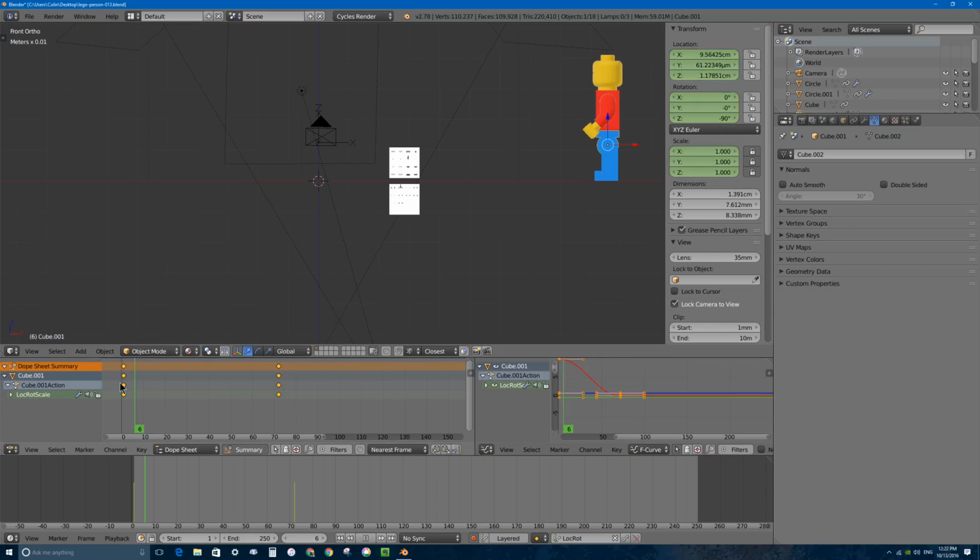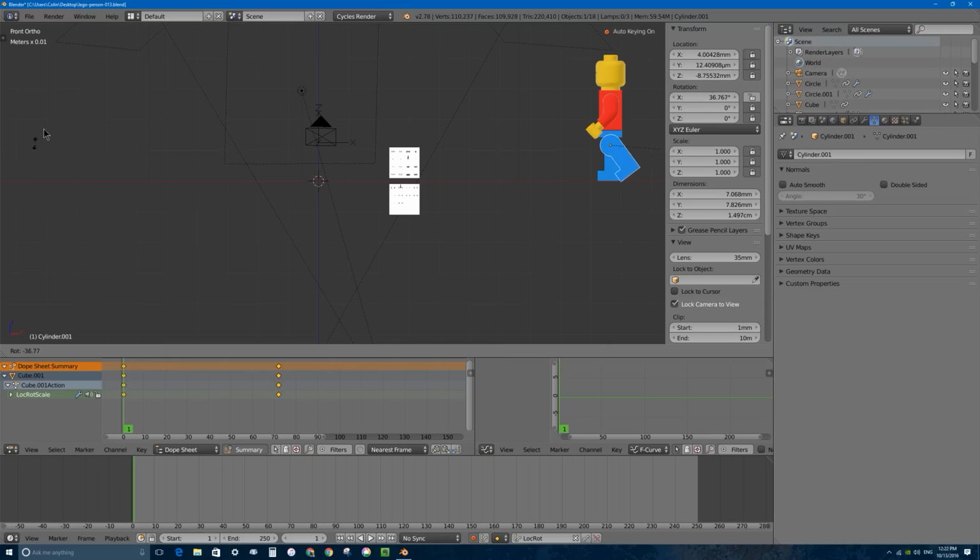Let's go ahead now and go back to our first key pose. We have blocked out sort of the animation in the most primitive way, but at frame 1 I want him to already be in mid-stride, so I'm going to grab each leg, I'll tap R, I'll move my mouse, and I'll put him in sort of a walking stride position like this, and maybe correct it just a little bit.